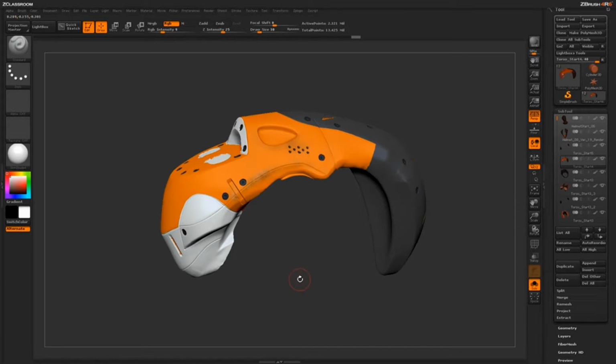Now, if you have a flat color, like we filled this in with an orange, I can actually come back in and set orange to bleed out or erase areas that I may have charred too much. So I'm just going to hover over the top of the model here and hit C on my keyboard. That's going to color pick that color of the model right there. Just hitting C will color pick anything that's visible on your canvas. So I'm hovering over the orange, and I can come in with Spotlight turned off, so I hit Shift Z to turn it off, and then bleed that effect out by applying that orange paint right on the surface again, and clean up any overstrokes that I may have made.